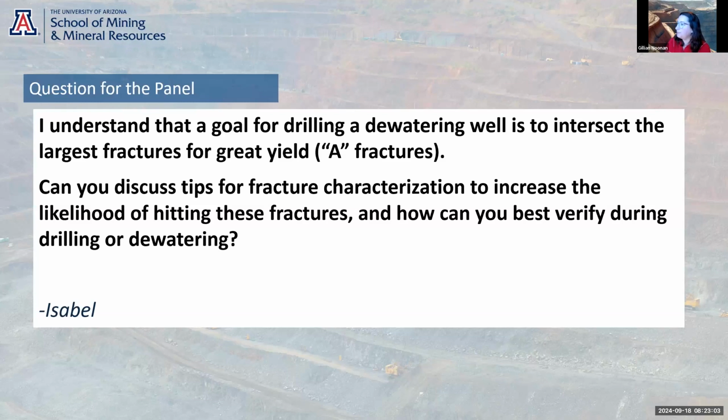Thanks, David, Charlie. I'll just add a couple of comments as well. Along the lines of what Jeff was discussing about pilot holes, if you drill the pilot holes with air, you can log the flow rate coming out of the hole all the time during drilling, and you can see kicks in the flow rate or changes in the flow rate as you drill, which usually correlate to the locations of the fractures.